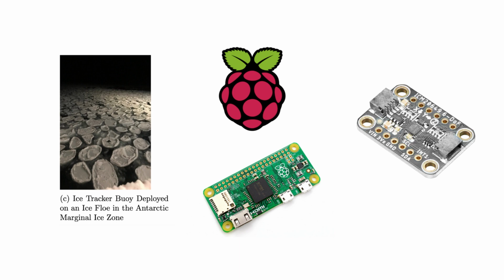The sensing device to be used is the ICM-20649, which contains 29 sensors for which data will be collected. Software is to be developed for running on a Raspberry Pi Zero to collect data from a sensing device, which is to be compressed and encrypted for storage on the device until it is eventually retrieved.